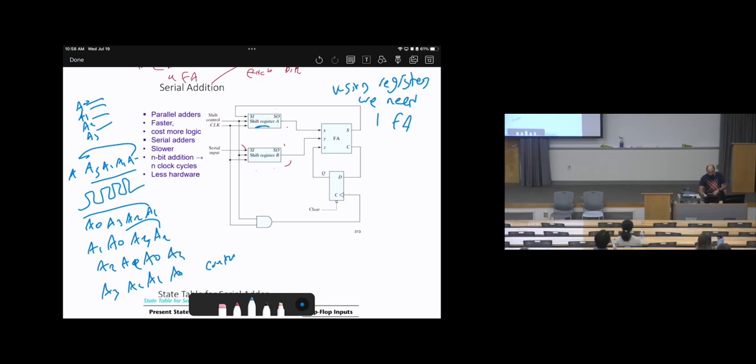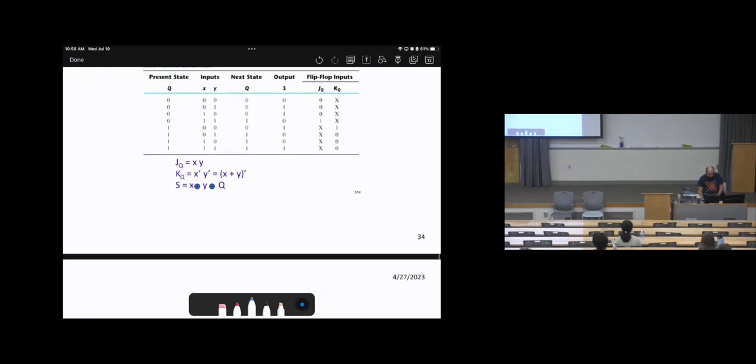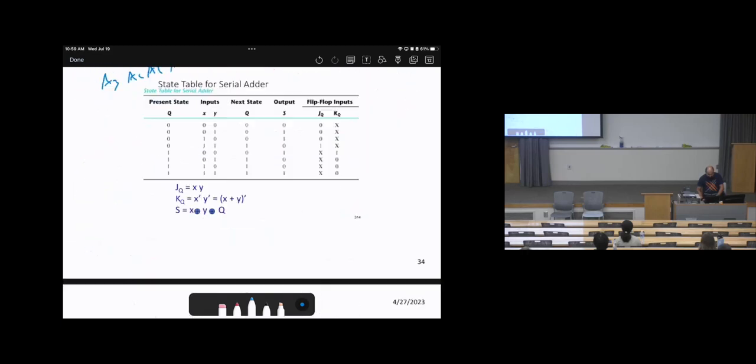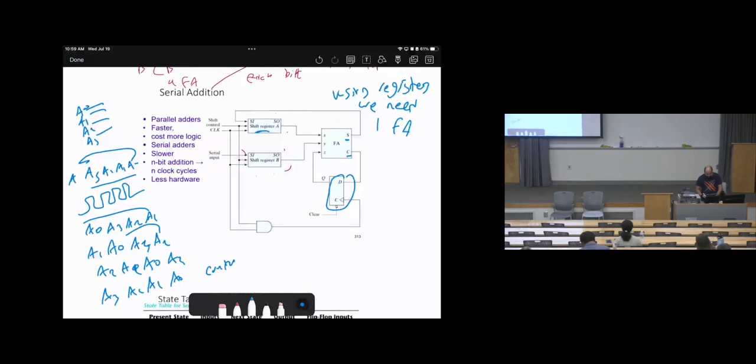So we can have sum and carry, then the carry will be stored to go to the next cycle. We need the carry bits to be stored so we can use them for the next cycle. We will not keep it as a feedback, because we are waiting for the next cycle to make the other addition. Therefore, we need to have a D flip-flop there. How we can design it, I think we don't have enough time today, so next lecture I will continue on how to make the design using this. Thank you.